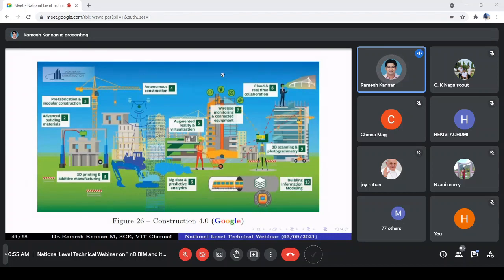Sensors in the parking area are very popular because when the car is moved, the sensors get triggered and the lights get switched on. When the car is stationary, nobody needs a light, so there are no people moving in a park or garage. Then there's no need for light, so it could be dark. This means you don't have to keep a basement lit for almost a day, so it is energy saving.